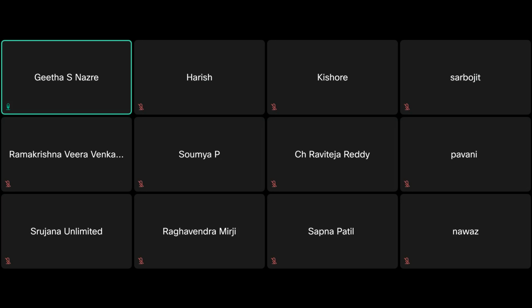Yes, ARM has the Ethos U55 NPU. So Streamline can tap that as well. Yes, of course. Because this NPU is given by ARM, there will certainly be counters in that as well. You read the data sheet of it, and there will be some counters as part of the PMU, which the Streamline agent will capture and show to you.